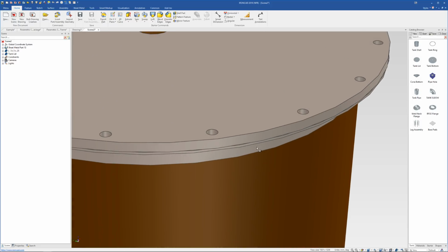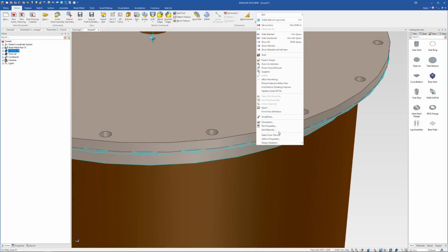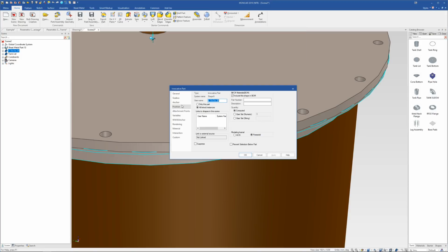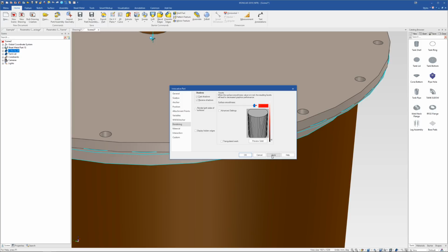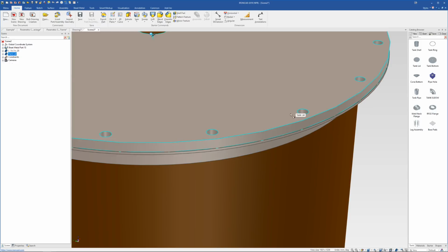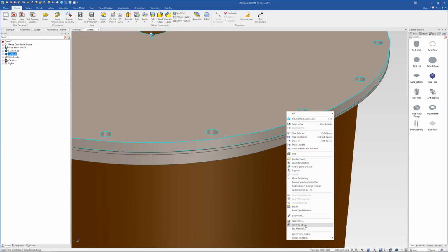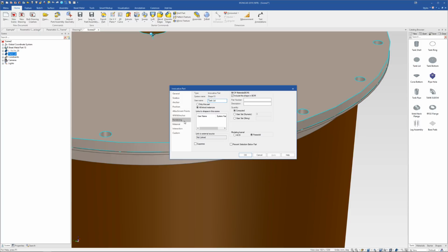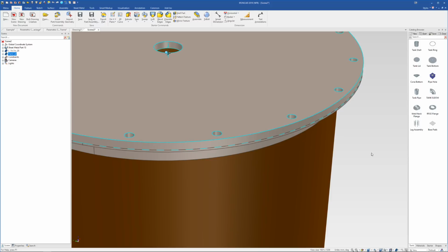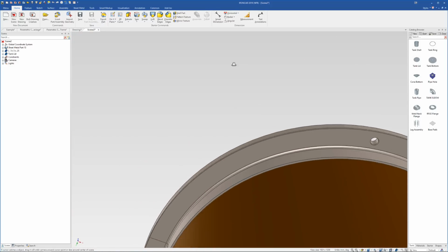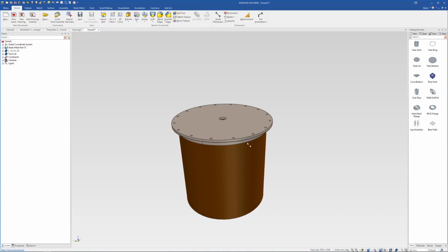What I'll quickly do here, though, is change the default rendering on these parts to a little bit smoother so we can see the alignment a little better. Generally, I default to 60. That's with a relatively powerful computer. The higher you go, the more computing power it's going to use on complex parts. So it's not worth going too high, but it is worth smoothing things out like that to get a better look at them as well.